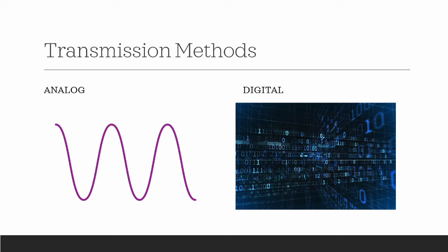If you're doing an event where you've got two channels of wireless set up and that's all that you need, you're probably not going to notice this. You're probably not going to need to take the time and figure out: do I need to do a full coordination, a full deployment, where I need to be concerned about intermodulation? When you're doing 15, 20 channels of wireless for a big performance and you've got backup channels and all of that sort of thing, intermodulation absolutely comes into play, especially as the frequency space, the bandwidth that we've got to work in for our broadcasting, shrinks and gets smaller and smaller, and is ever evolving.